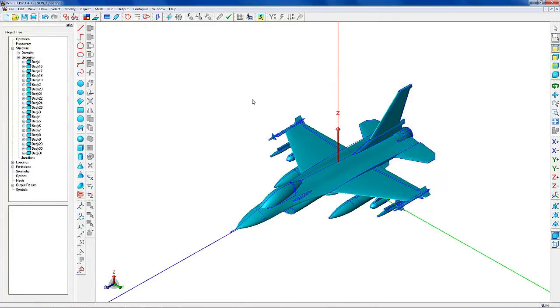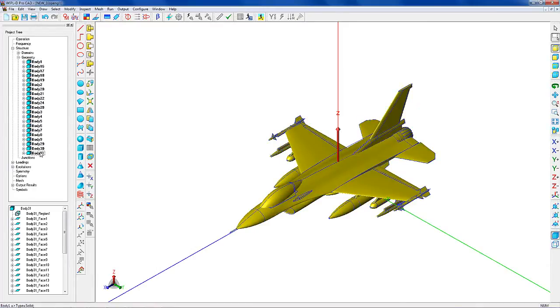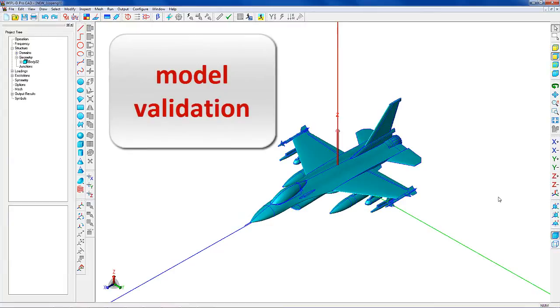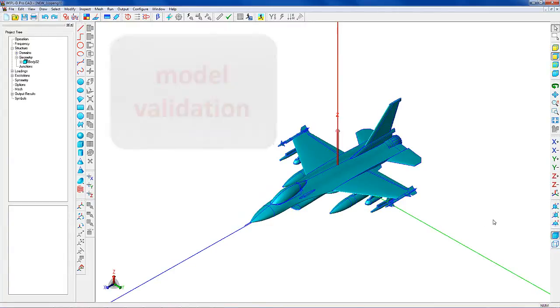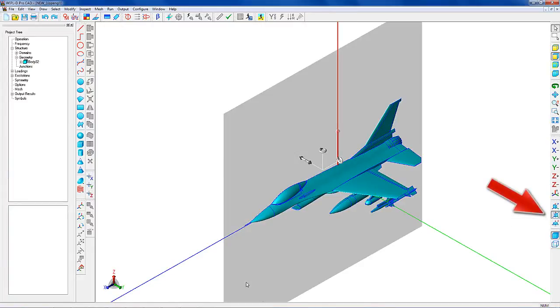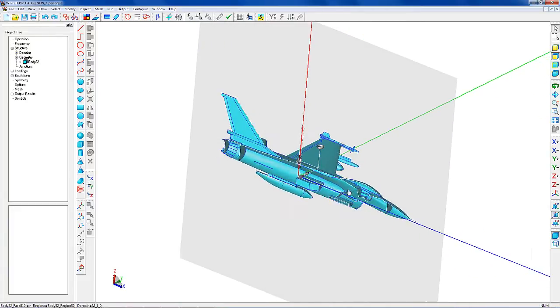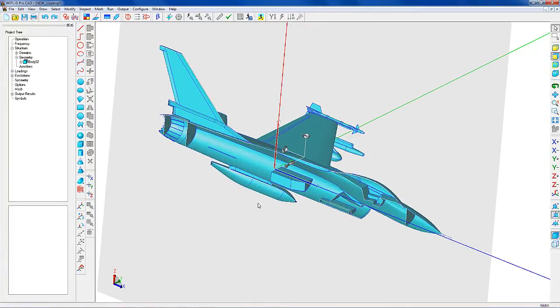After the healing process, all bodies comprising the model should be united into a single body. The process is simple. It consists of selection of all bodies and performing the Boolean operation unite. After the union, a number of interior faces remains. The presence of these faces can be illustrated if we remove the preview of half of the model located in the negative y coordinate. That leaves half of the model displayed.